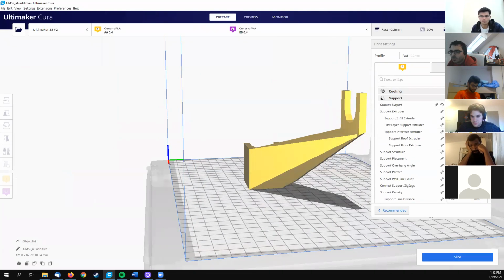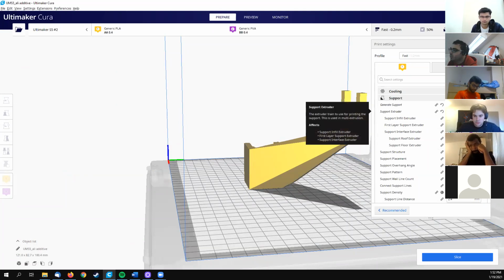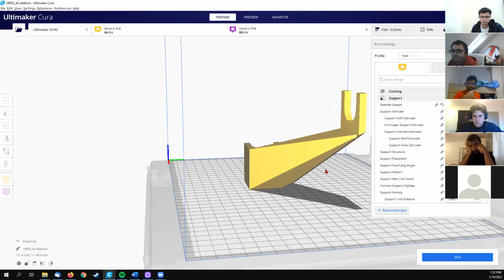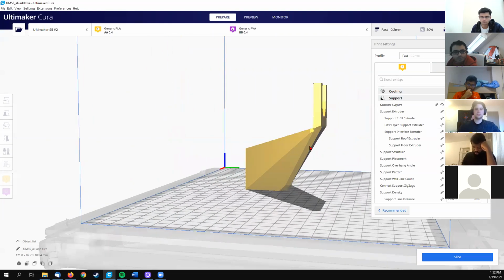by default, the support is going to be printed by nozzle number 1. If it's not, you have to select it. So it could be nozzle 2. So be careful that you switch it to nozzle 1. Everything built here needs to be extruded from one single nozzle. Assume that we remove this, it doesn't exist. So now we're working with supports, and we can slice.